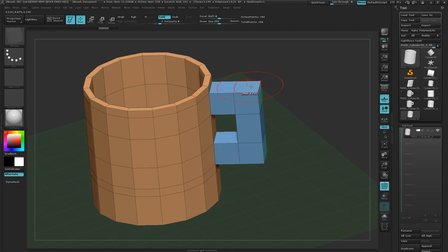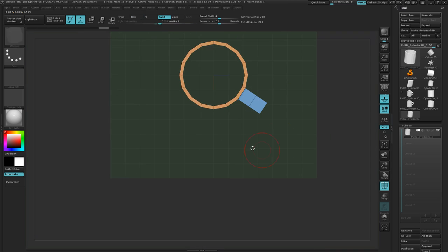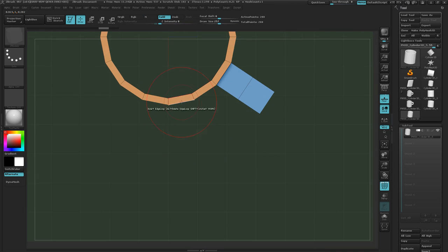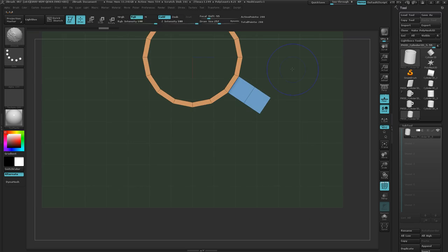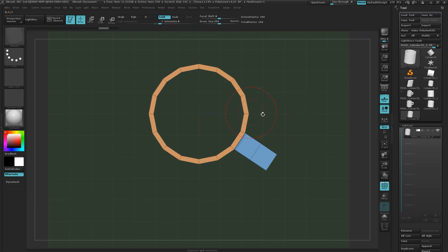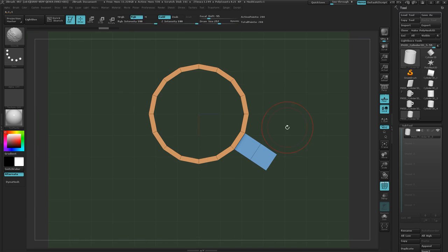So now let's move these, or first let's get this thing rotated, because if you're looking at it up here, you can see that none of these flats are orthogonal. The points here are at the top front, or in the XY direction. So to do that, I'm going to rotate this thing around that center axis.